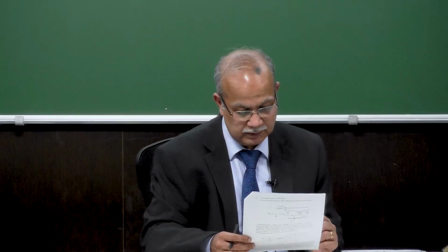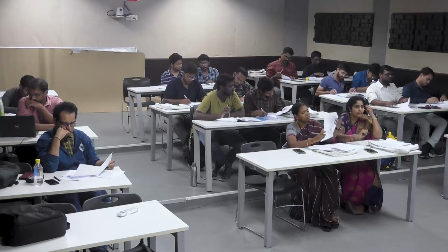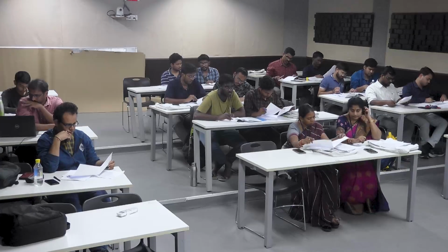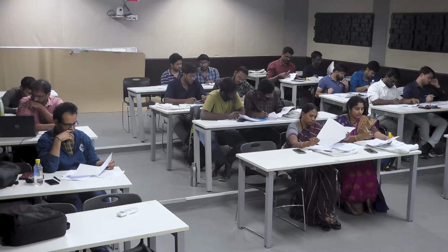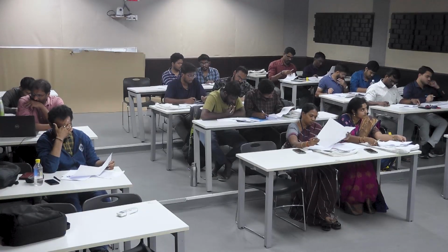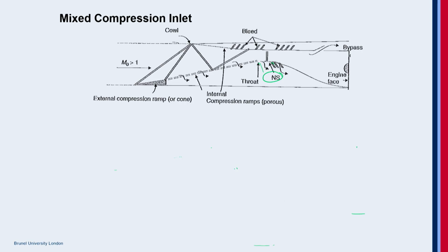The inlets of the most advanced fighter aircraft are designed with a two-dimensional wedge-type diffuser. These inlets use a combination of external and internal compression systems, as shown in the figure below, to decelerate the flow using 3 shock systems, 2 oblique shocks and a normal shock, to bring the flow to subsonic condition. If the flight Mach number is 3, then calculate the following. Calculate the overall total pressure ratio. Calculate the overall static pressure ratio. And the overall total pressure ratio if there was only one normal shock.